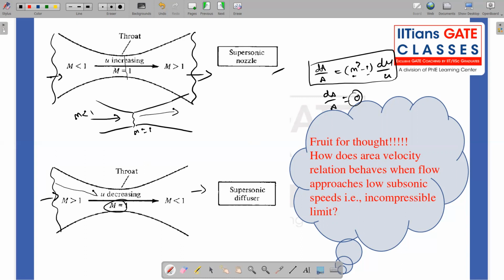applications, right? Like even in wind tunnels, in aircraft or rockets. So whenever we want a supersonic exit, we will have a converging-diverging duct. Why? Because that is how physics told us. Because of that only we designed this and it's working, right? These are all purely dictated by physics, yet we can see the applications, through which supersonic aircraft are flying, rockets are flying out of the atmosphere, or wind tunnels are working fine.